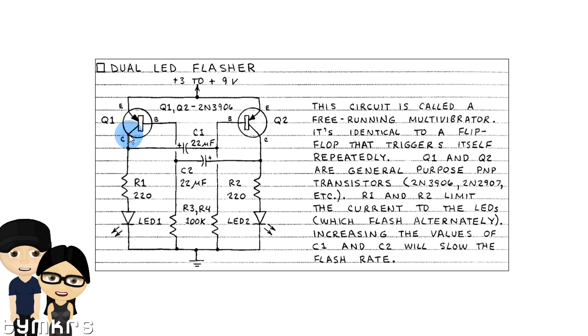But this particular circuit uses PNP transistors, and PNP transistors are slightly different from NPN in that the basic function is that the voltage at the base has to be lower than the voltage at the emitter for the transistor to conduct electricity from E to C. And charge from the emitter, or from the power source, puts out a trickle of current through B, and that trickle of current is amplified through C. Does that make sense at all?